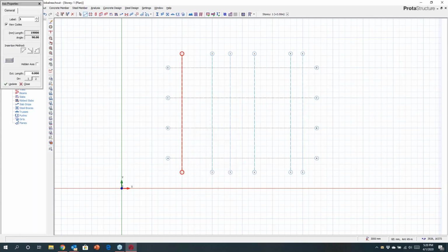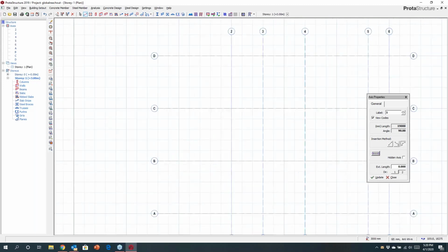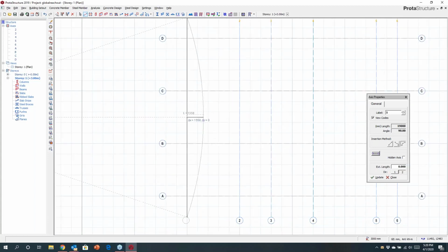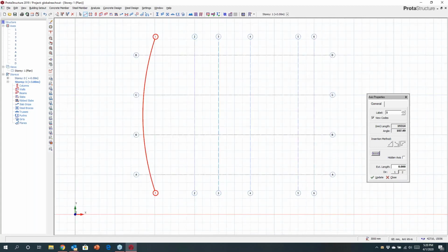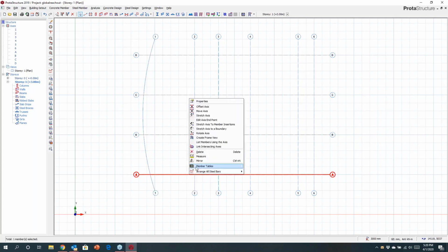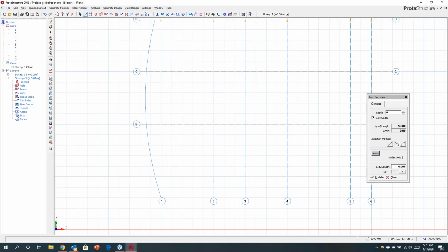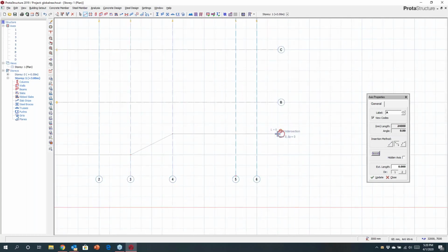You can work with these axes to make changes. So if I decided that I don't want to work with a straight grid line, but in this instance I'd like to create something that's perhaps curved, this is all dynamic and you can make changes. So I can key in maybe a chord length, and then it will draw that axis the way I want. If you wanted to make other changes, perhaps you've got a really unusual facade or something a bit different, then you can use what we call linked axes, which are dynamic, where you can create whatever funny layout the architect might have set up.